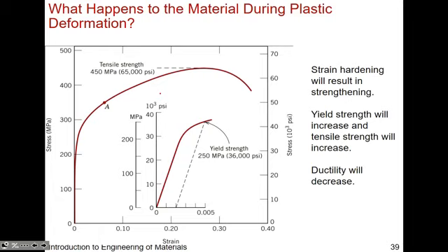When we take a look at this stress strain curve, we say, okay, if you deform a material within its elastic region, somewhere here, let's say that. Beyond that, sorry, let me switch colors. Beyond that, you're plastically deforming your material now. So you could see that the strength of a material is actually increasing as you deform a material.